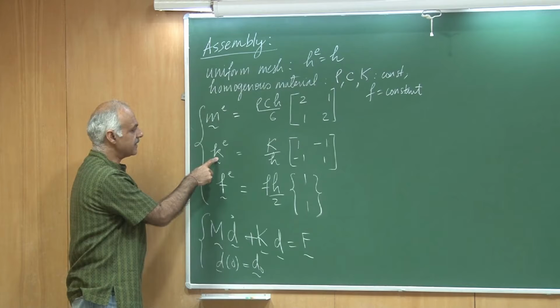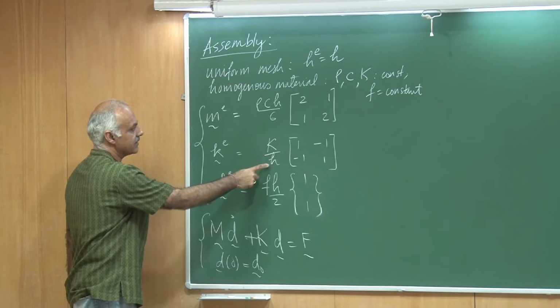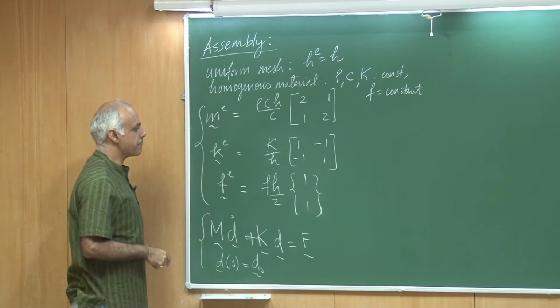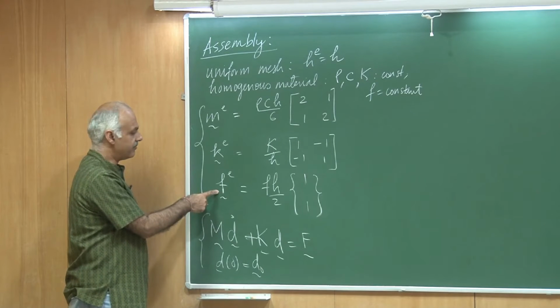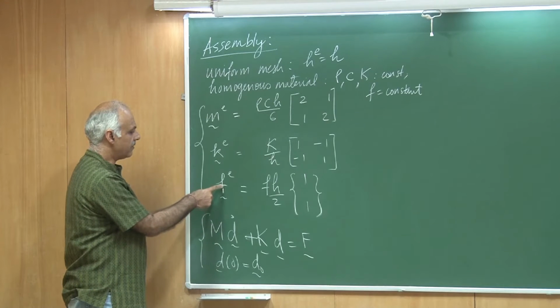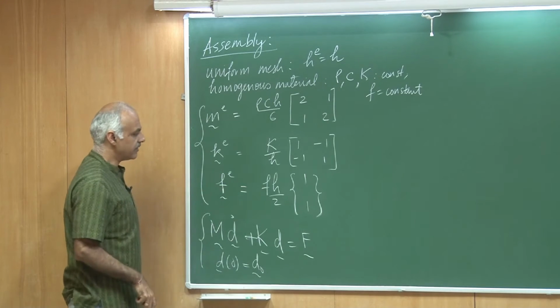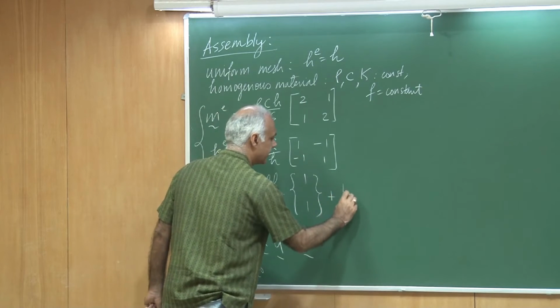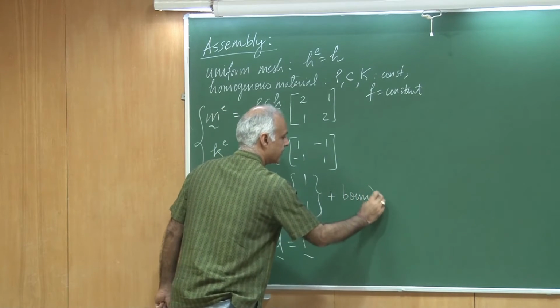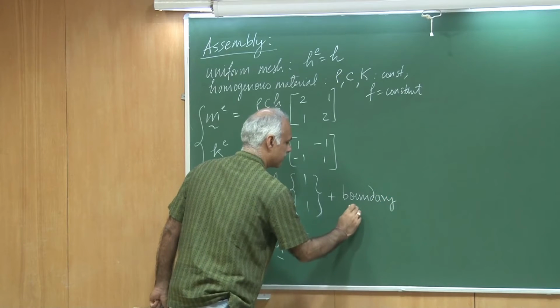That is your stiffness matrix. So, constant heat conductivity, that is your element length, and then the force vector gets fairly simplified. We have these terms Fh by 2, where F is the heat source, and of course, there would be the boundary terms which we are going to not worry so much about.